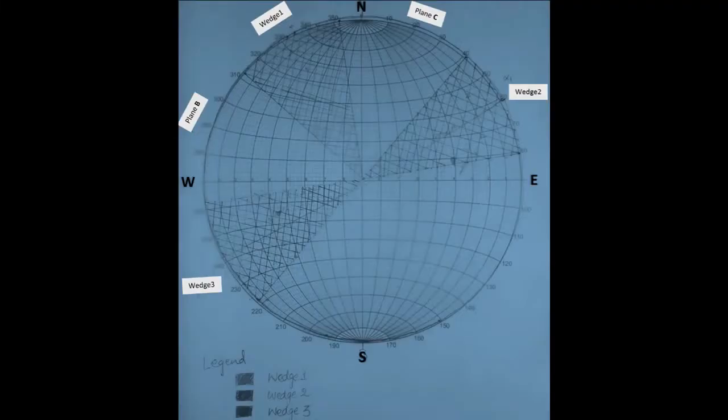To verify the slope stability analysis of open pits and highlight the problematic areas, we draw three joint set planes on StereoNet. As you can see in this picture, the color diagram shows the failure areas. That failure occurs in the plane within plus minus 20 degree, and we have to install the support system given by the SMR support guidelines to these color shaded regions.